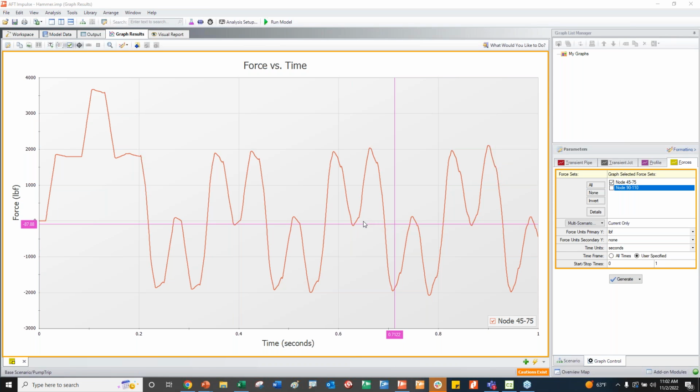Can you use B31.1 for this? Yes, B31.1 can be used for the analysis, with the same criteria as B31.3. B31.1 establishes a maximum stress in the pipe.